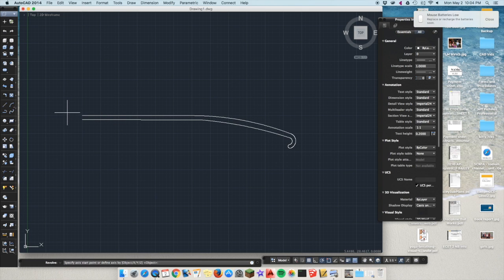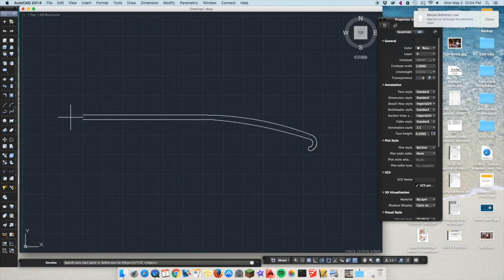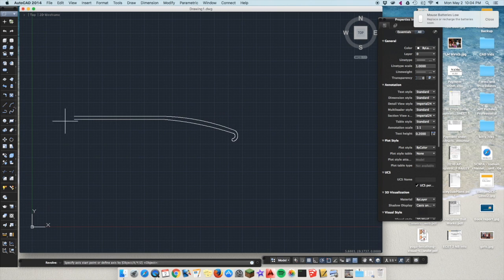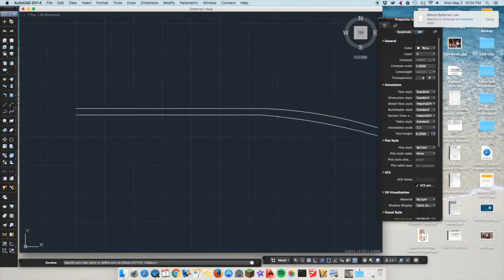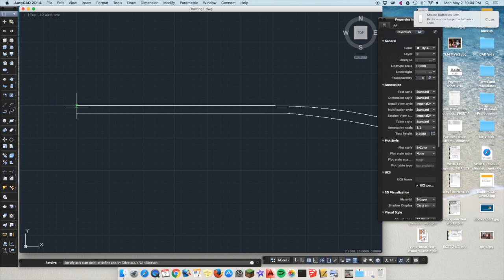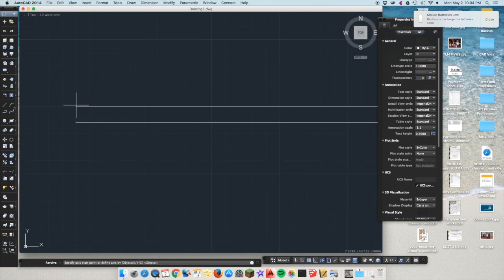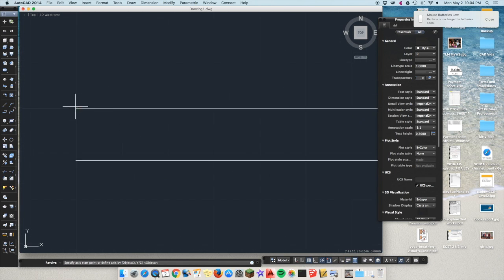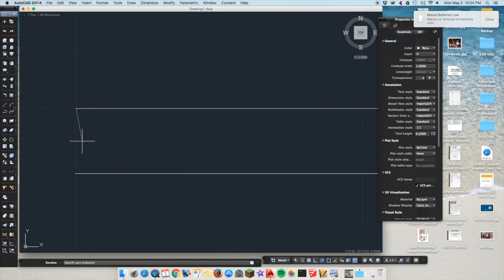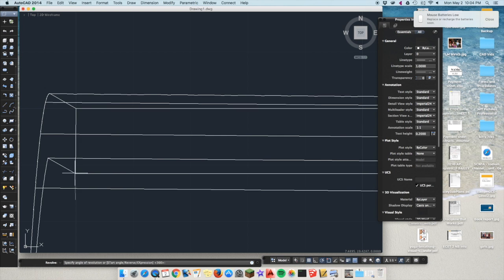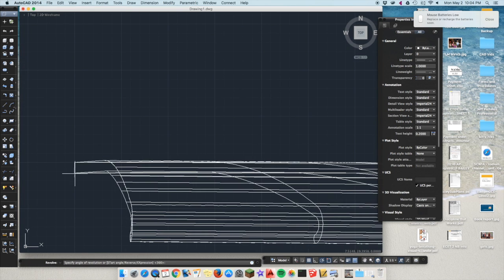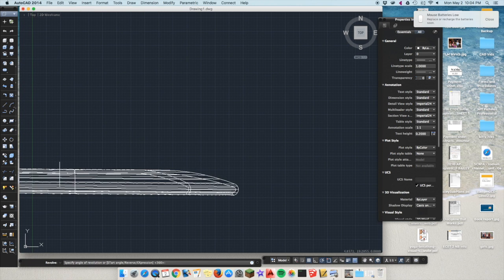Then I'm going to select the axis or starting point. So we want to rotate this around the y-axis. I could just type y probably and hit enter, but I can also choose two points along the line. So I'm going to do this point, the end point of that, and the end point of this. And now you can see your screen probably freaks out.